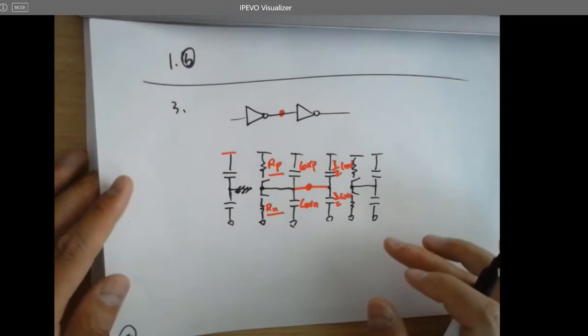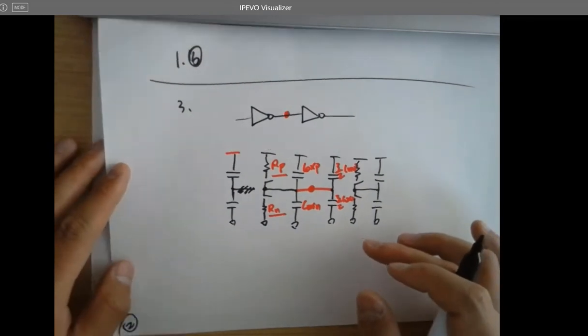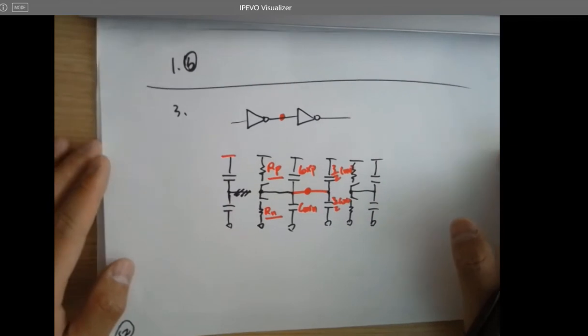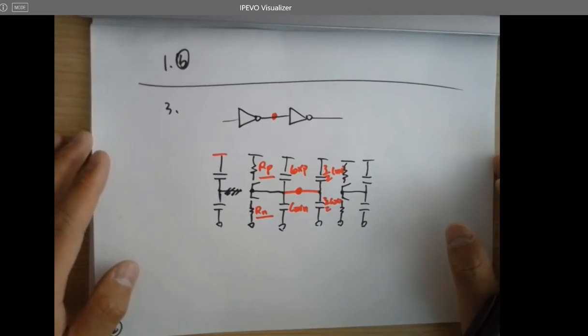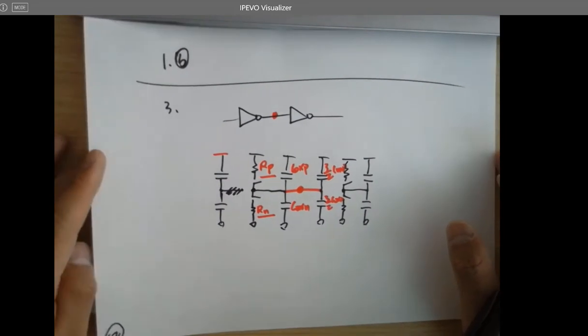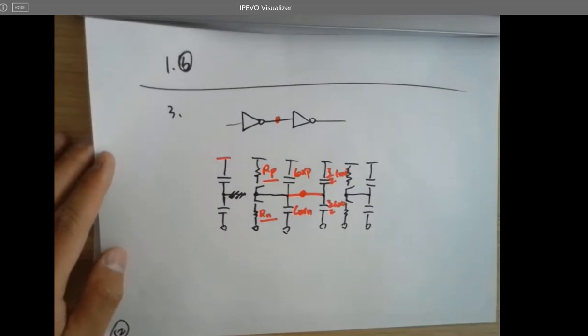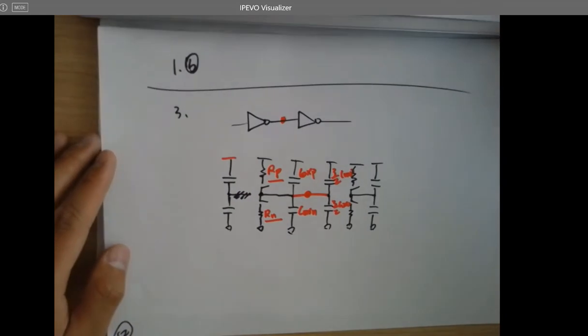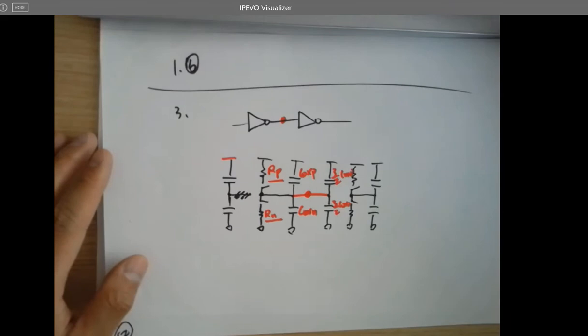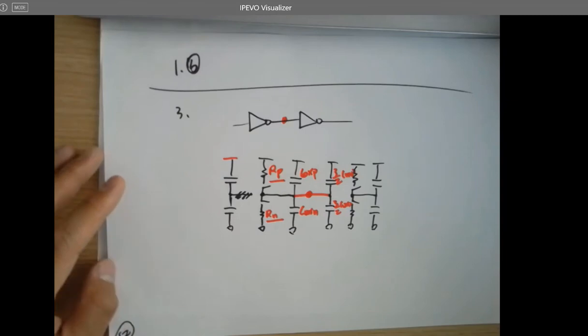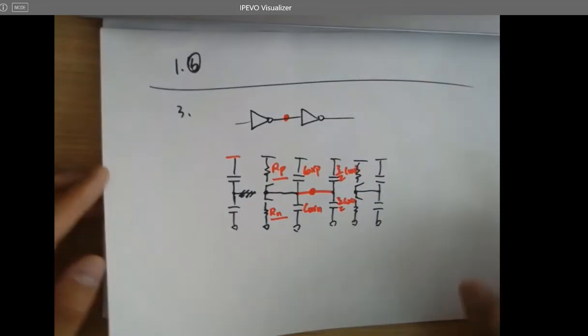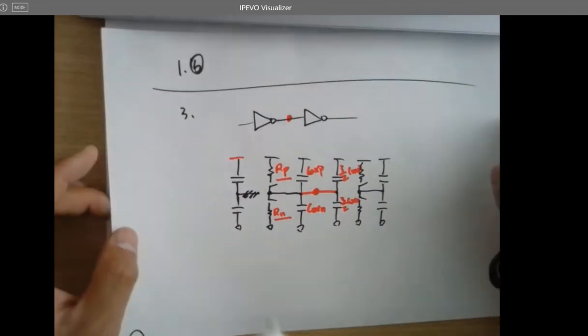And you don't need to worry about the capacitance inside the transistors because it's relatively smaller compared to the load. So just look at the load. It's how much? Like 2 pico, right? Looking at the table, all the capacitances of the transistors are at the femto level, so the picofarad is way higher. You can directly ignore those capacitances. So the load capacitor will dominate.